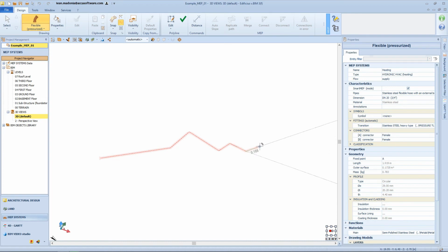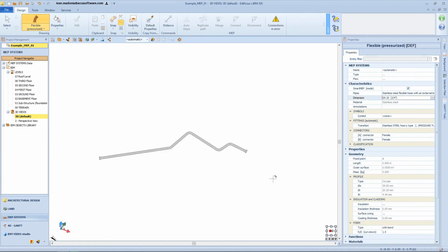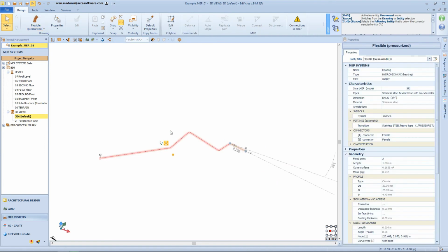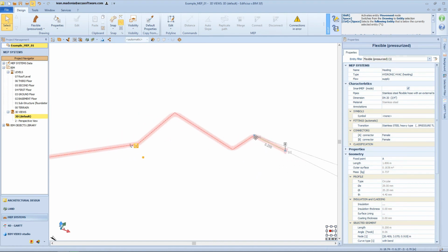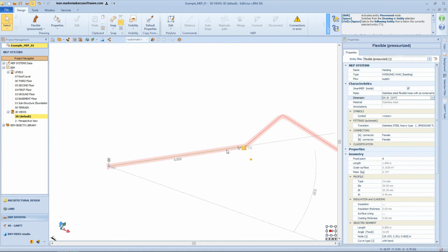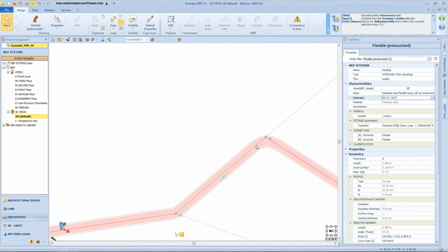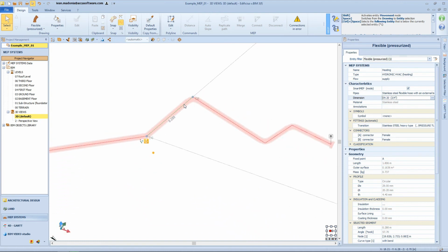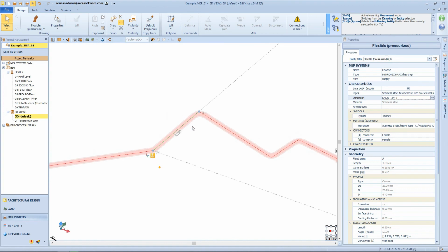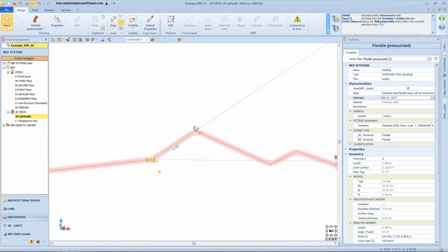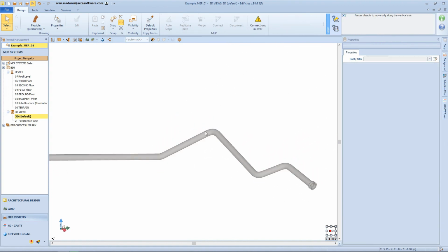A broken line is therefore associated with the path of the hose that joins the segments of the various sections that are defined in the modeling. It is important to underline that the length that defines the section being drawn is that of the segment that joins the 2 ends of the section and not the actual length of that portion of the hose, which instead also includes the curvature. Furthermore, the sections that are drawn from time to time allow you to define only the path of the flexible, therefore there will be no joints at the nodes.